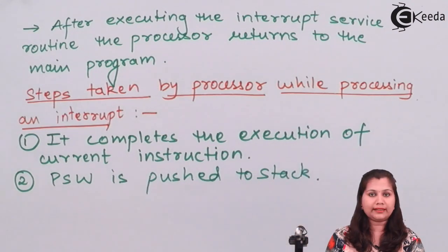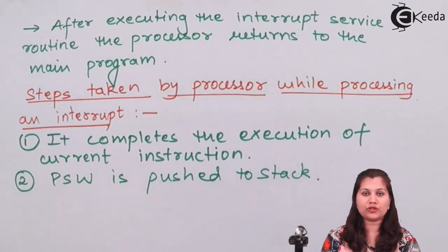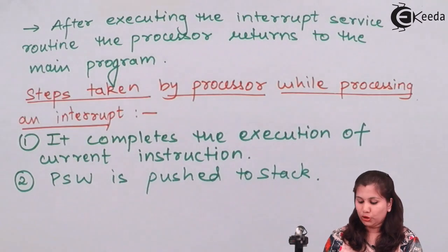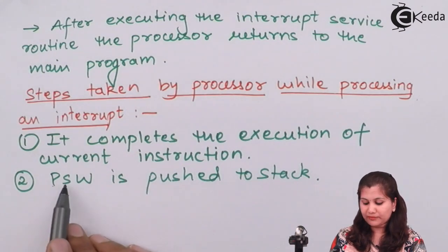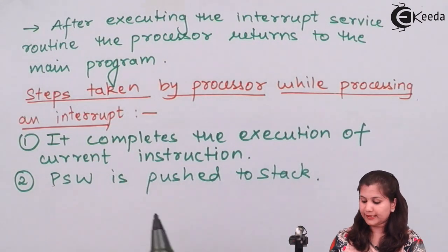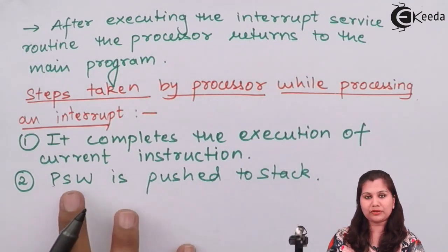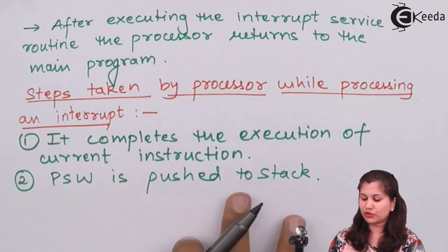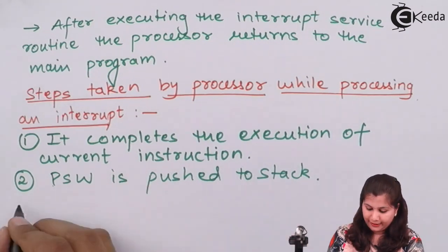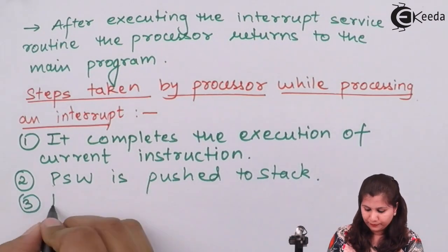To store the contents in the stack, we have the instruction PUSH. Here I have written that the program status word is pushed to the stack. Pushed means the contents of the program status word, the flag register, are stored in the stack. Next step is to push